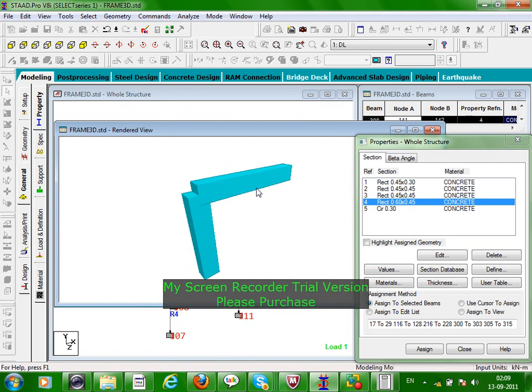A beam is considered always from center to center distance. Remember, whatever you provide by default, this geometrical design is always center to center. Note down why I am talking about this: somewhere you will never find the column exposed in a wall. You will always find it flush. So you have to change this orientation by editing.